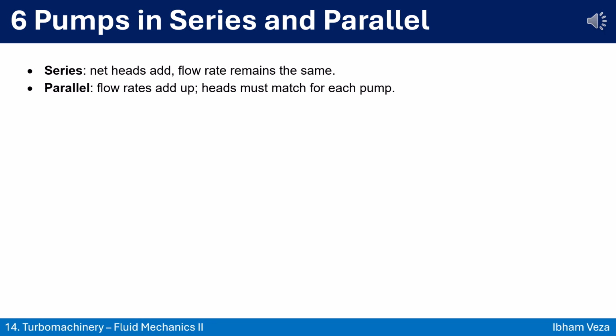Choosing between series and parallel depends on the system's specific needs. Do you need to overcome height, or do you need to increase the flow capacity? These arrangements allow pumps to be flexible, scalable, and responsive to changing demands. Understanding how to use them effectively is essential for designing resilient and efficient pumping systems.